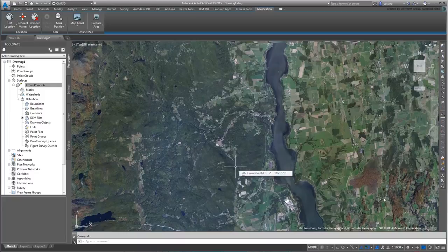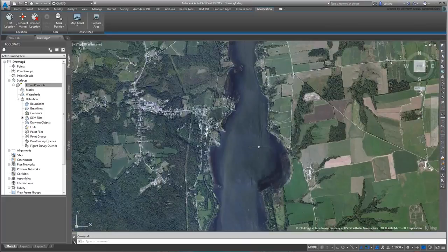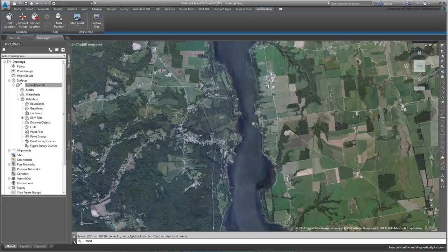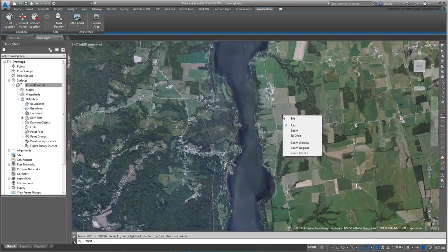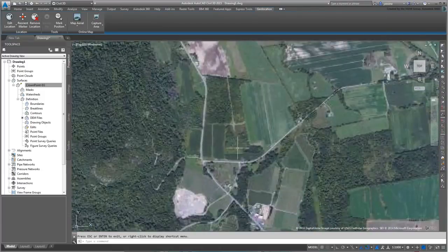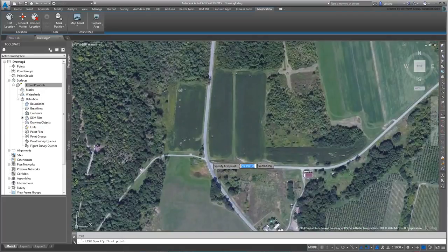Next, you draw a rectangle over the area of interest using the Rectangle or Rec tool to that effect. It is important that the area you select here is the same one you defined when you created the aerial image earlier. This ensures that the ground texture image you created maps itself properly to the extents of the created surface. First, draw a couple of lines to define two corners for your rectangle. Start the first line at this intersection point. This is the same point you use as a top left corner for your ground image.